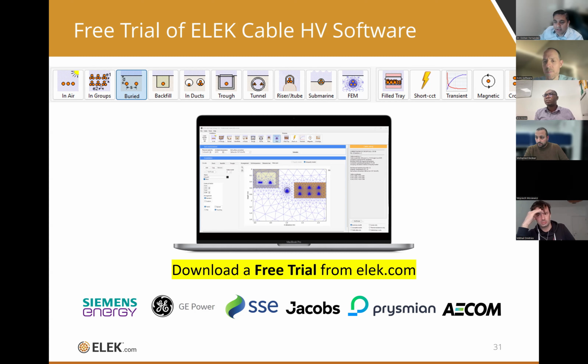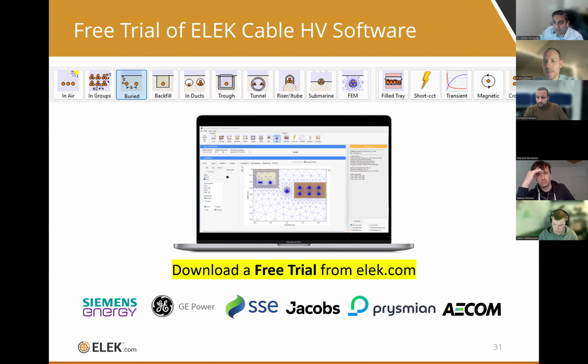I think there's one last question. How to model pressurized fluid filled or cooled HV cables? I assume it's pipe type cables. Yes, we can do pipe type cables. Even TB880 has two examples of pipe type cables, I think low pressure oil filled cables. We can do that in our software currently. We can do all those cables, including in FEM as well.